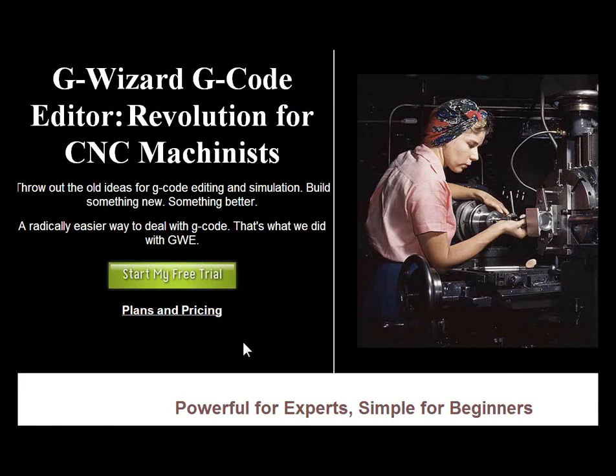Basically, if you can find problems and fix them while you're sitting there at the CAM program rather than at the machine, it's better. You're going to save yourself some time. You might save yourself some heartache in terms of machine collisions and that sort of thing. And so it's just a really good idea. A lot of different shops make it a requirement that you run a simulation before you run the G-code on the actual machine.